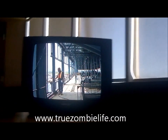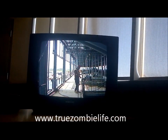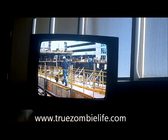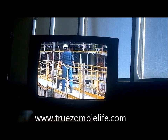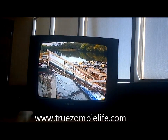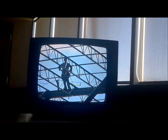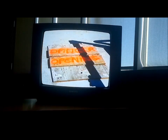The first step is to identify fall hazards in your work area. Look for situations where you could fall more than 3 meters. Could fall more than 1.2 meters where the work area is used as a path for a wheelbarrow or a similar device. Could fall into operating machinery, or into open water or another liquid, into or onto a hazardous substance, or through an opening in a work surface.